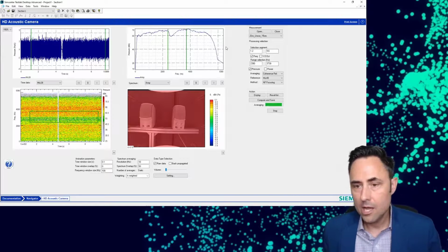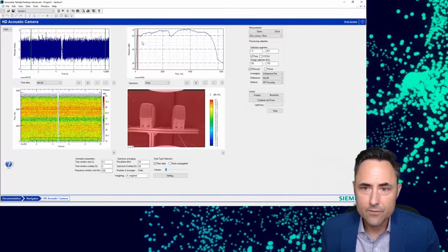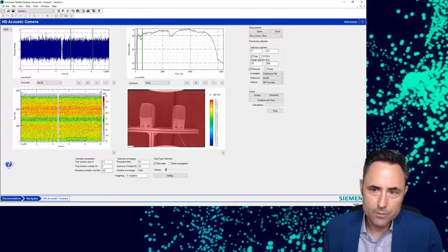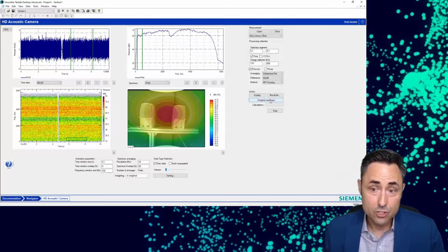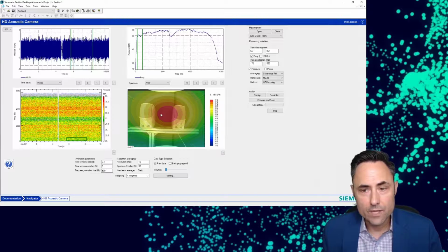One of the benefits of this technique is this: if I show you what the localization in beamforming looks like for some low frequency, I've selected 170 hertz to 550 hertz, and I'll just grab some time here. I'm just saying, show me where this low frequency energy comes from. Beamforming is kind of locked in terms of resolution to the wavelength of sound that you're trying to localize. So you see I get this really generic answer for this frequency range.